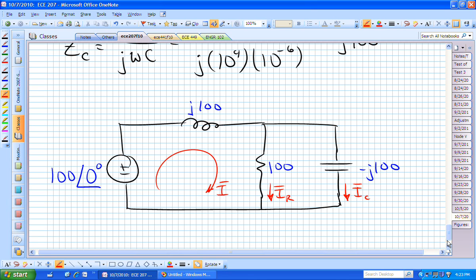And that's why we're able to do this. We know the transients are going to go away. We're going to be in sinusoidal steady state after 5 time constants, which isn't going to take very long, and now we can just play with sines and cosines. That's why we're able to do what we're doing, because we're saying we're going to forget the transient and just look at the sinusoidal steady state behavior of this circuit.